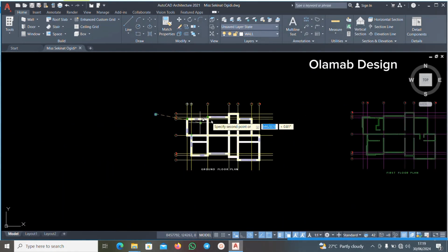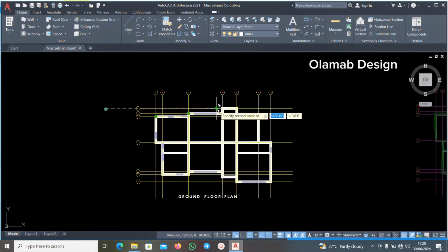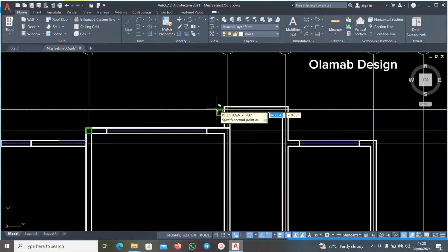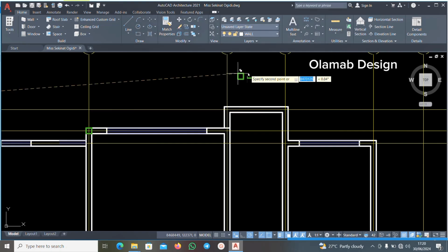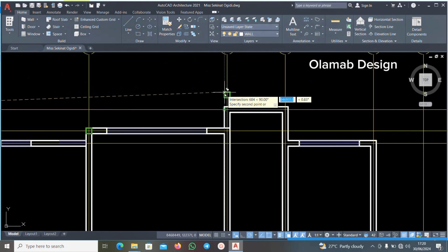And make sure, if you remember, I explained some things in my past videos for you, that whenever you are modeling, if you use your ground floor plan and place a column, your column will project down to your ground floor. Like for instance, whenever you export any drawing or start modeling on your portal structure, if you model on your story 1, it's going to project down to your ground floor. So you need to know that. It means if I place any column at this point now, it's going to project out on my ground floor, which is very bad, meaning I don't need a column at this point for now.